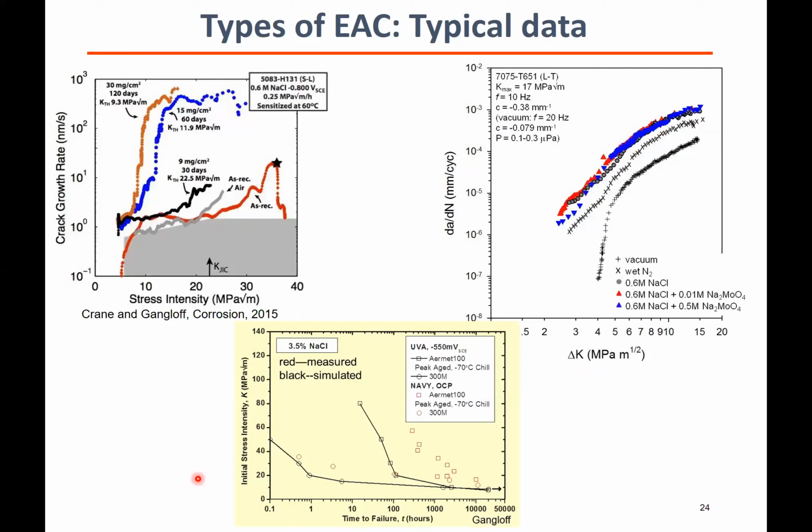So here's some example where you could see crack growth rate versus stress intensity factor, similar to the hypothetical plot that you just saw. And you could see here the material that's been collected in the Fontana Corrosion Center. You could see here the crack growth is increasing, and the material is failing well before what you expect.